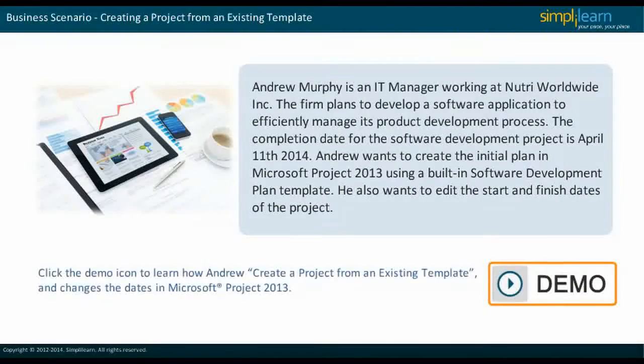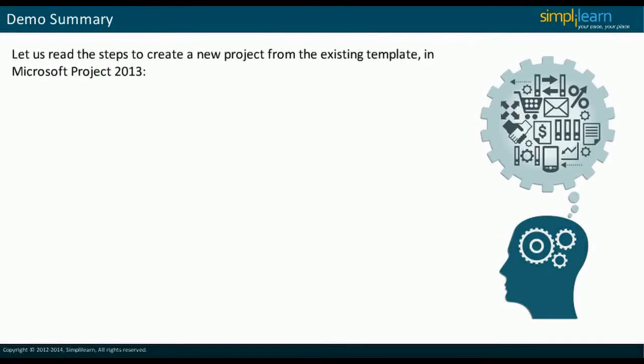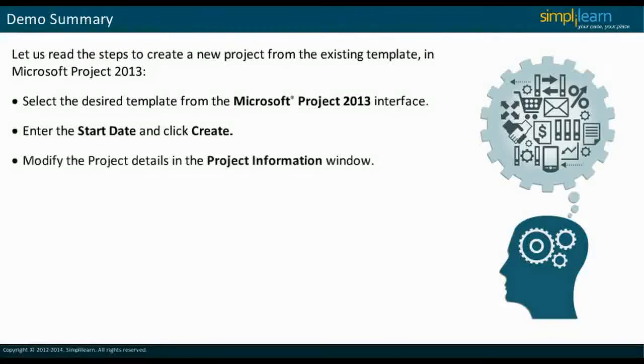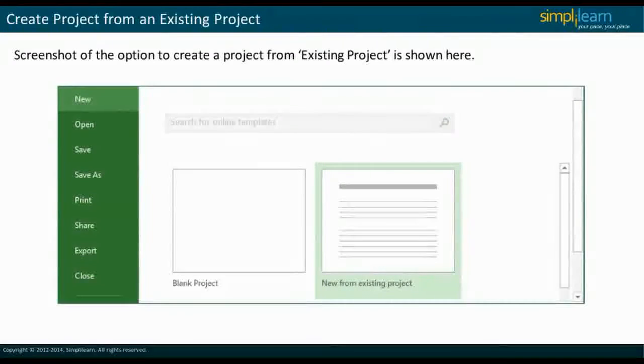Click the demo icon to learn how Andrew creates a project from an existing template and changes the dates in Microsoft Project 2013. Let us read the steps to create a new project from an existing template in Microsoft Project 2013. In this slide, we will discuss how to create a project from an existing project.